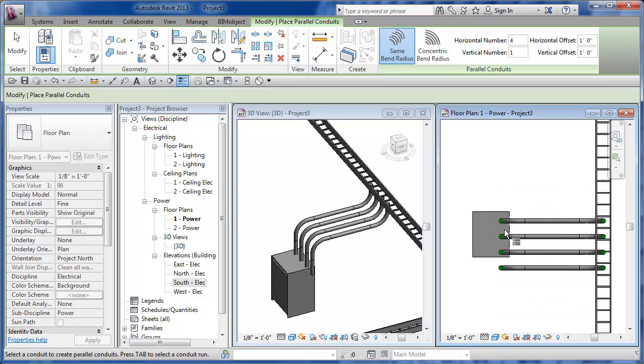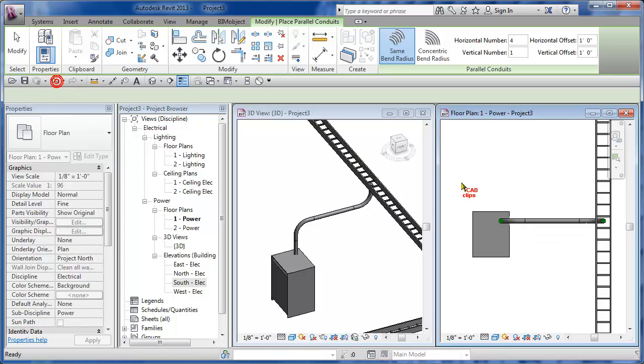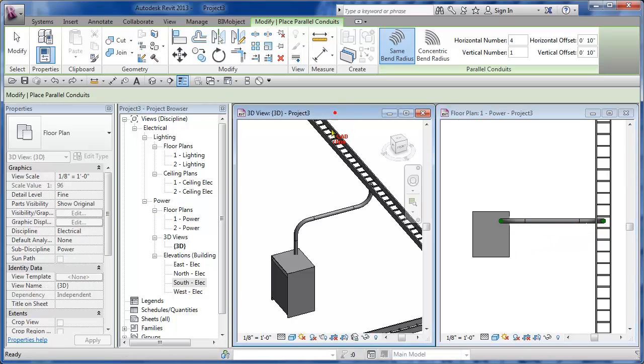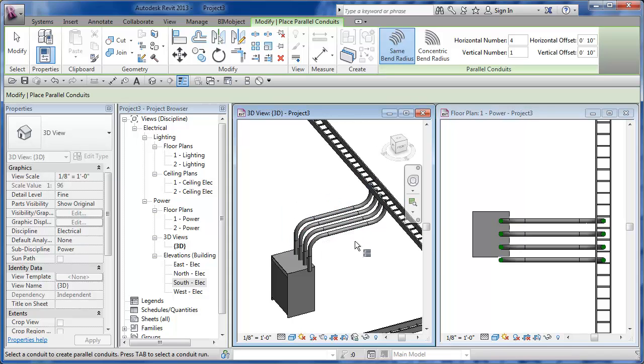And I'll say, well, you know what? The spacing is off. So I'm going to say, okay, undo one more time. And then maybe I'll set this to be 10 inches. The vertical doesn't really matter because I'm not using it, but I can plug that number in, and then I can go over here, and I can even do it from here. I can hover over here, and notice the side you want it on, and then tab and click, and in it goes.